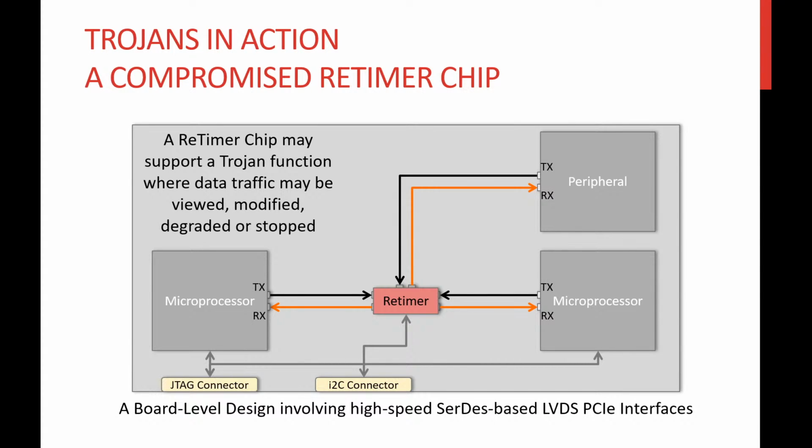So one strategy for opportunistic hardware security attacks on the board or system is not to target the big complex chips in the system, as they already go through extensive scrutiny during the design and test, but it's about attacking the small, ubiquitous support chips in the system. These types of chips can include functions such as voltage regulation, clock extenders, signal spreaders, and other chips that allow the large, expensive major chips to operate in a stable environment and enable them to communicate with each other.